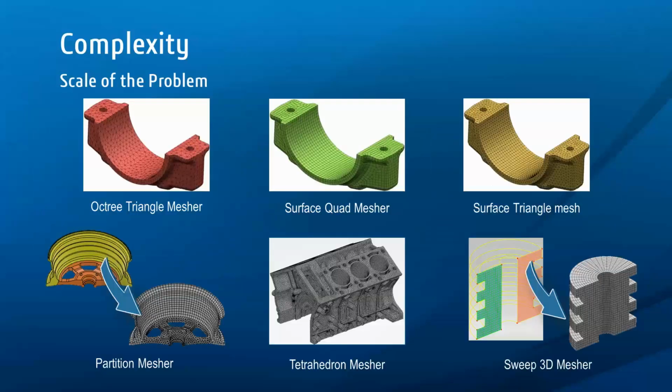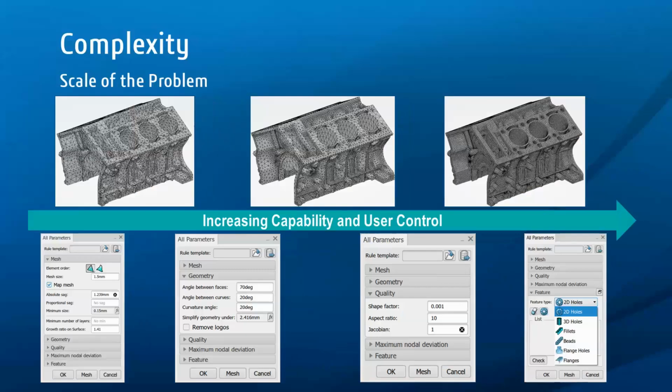The product's design and the scale of the problem being analysed can also require differing levels of mesh control to best conform with geometry and achieve the required results accuracy. There is a wide selection of 1D, 2D and 3D meshing algorithms available to the user to define the discretized nature of the structure. You can define beams, shells using quads and triangles, or solids using hexes, tets and pyramids using these algorithms. These algorithms offer differing levels of surface conformance and performance trade-offs.